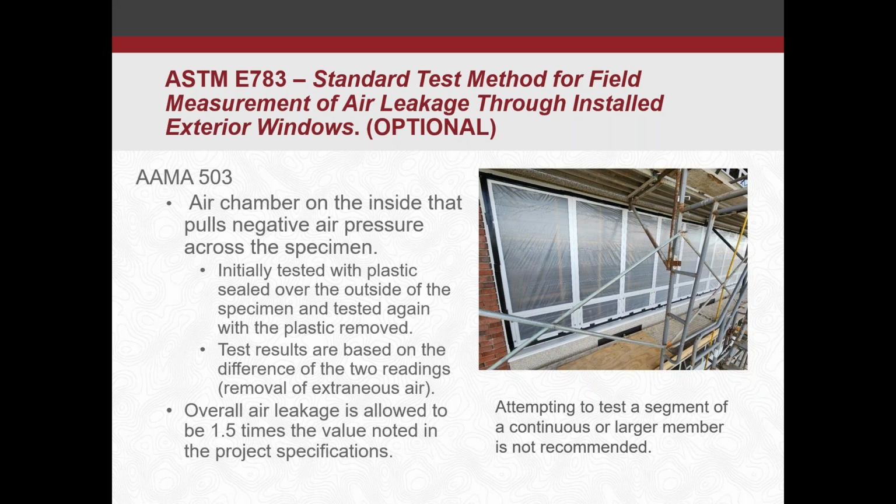So if you picked up on the fact that this said optional air leakage test, the reason for that being sometimes for storefront and curtain wall, depending on size, it may not be feasible to take an air measurement test or a leakage reading on the specimen, especially when you try to segment out a portion of a larger area.